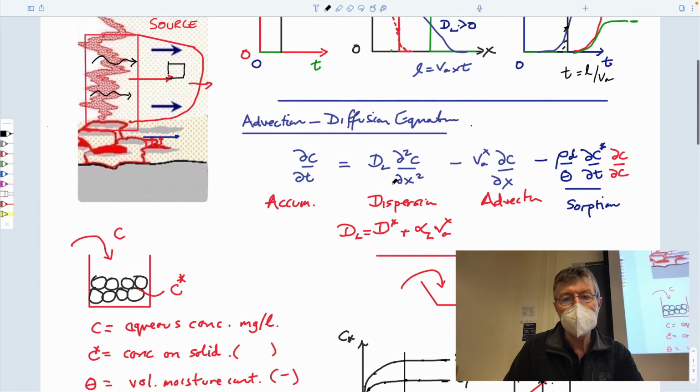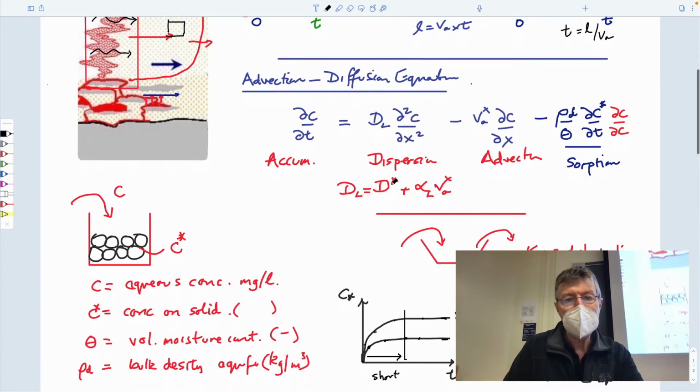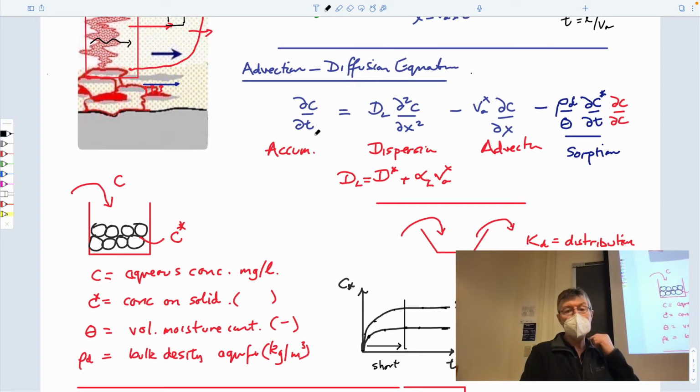And so what we can do is we can take our advection diffusion equation, or dispersion equation, which we had before. Accumulation is equal to the mass in minus mass out that occurs due to Fickian diffusion, and the mass in minus mass out that occurs by advection. In other words, a beaker with ink in it being carried across the room, you're advecting that ink by the movement of the water that's carrying it in a beaker. And so that's exactly what advection is.